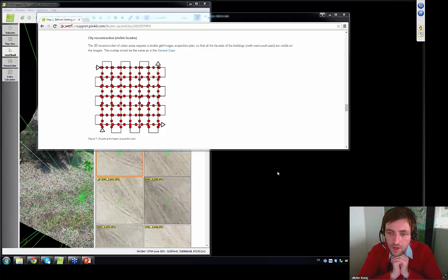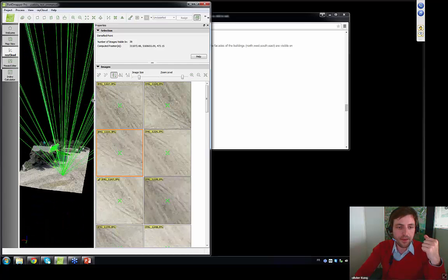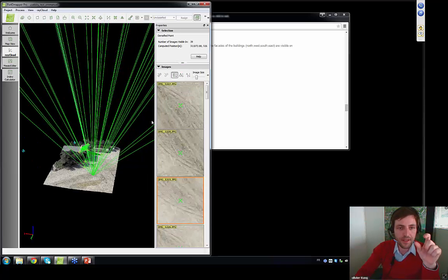Okay, another question. When using GCPs as checkpoints, do they still need to be marked manually in the ray cloud, or can they be left completely unmarked? Very good question. In the current process of the software, we require them to be marked. If they are not marked, it would just be an elevation, and we would not be able to compute the horizontal shifts, only the vertical shifts. So it's not recommended.